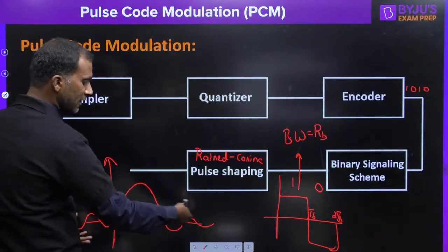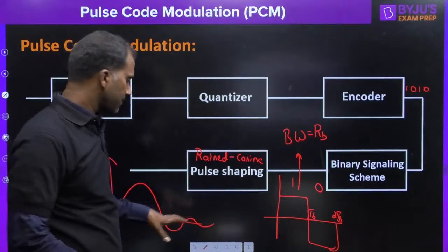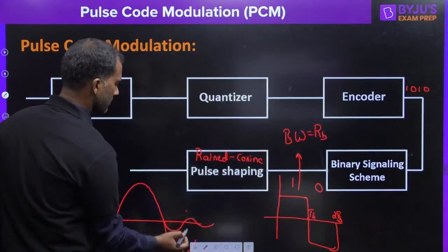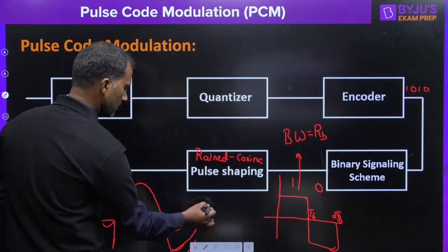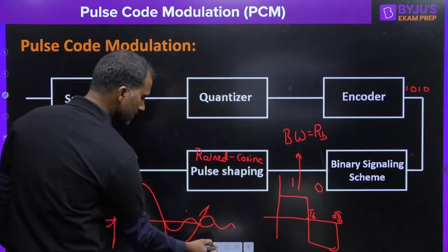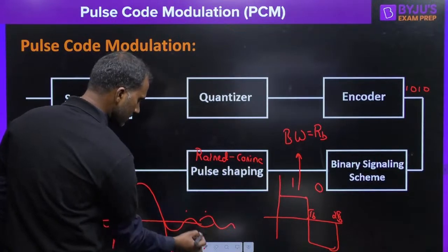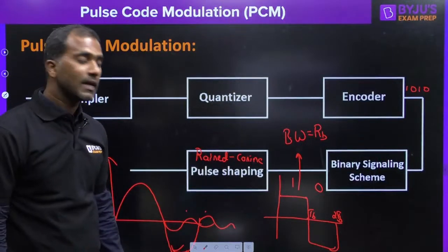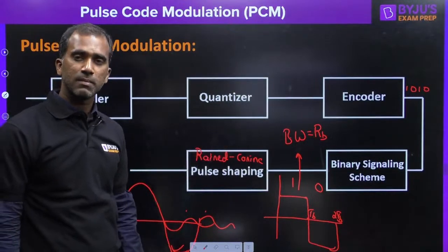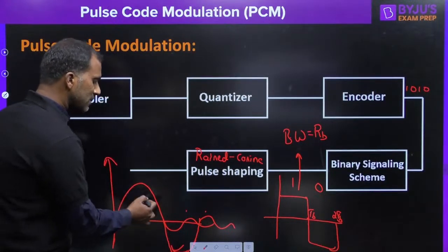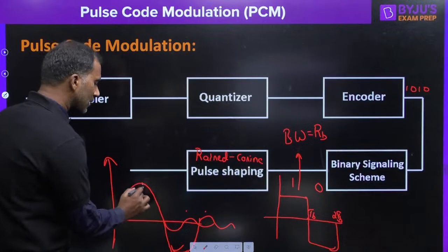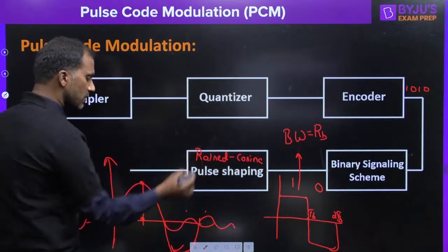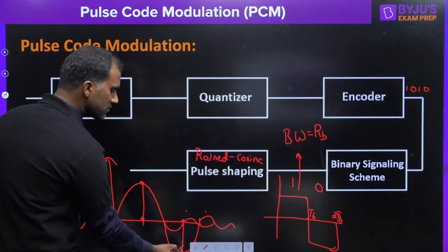Sir, it is interfering now already. Yes, it is calculated interference. So the next one is something like this. It looks like the first pulse is interfering with the second one, but care is taken while we design this, in such a manner that one pulse looks like it is interfering with the next pulse, but it is not interfering at the required instant of time. See this one? When you're talking about the first pulse, we sample at this place, we get a positive sample, and we understand it as 1 bit. We sample at this instant, if we get a negative sample, we understand it as 0.